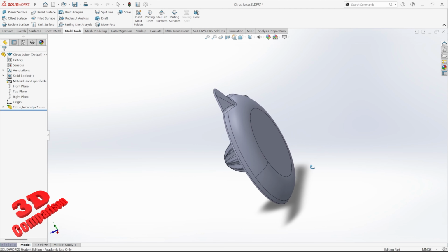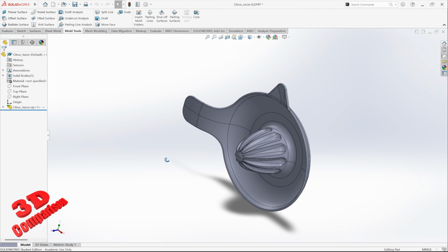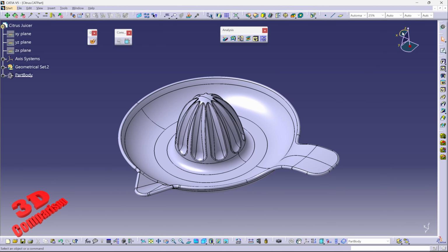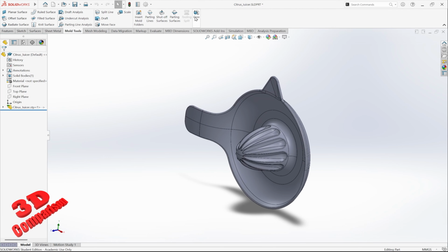And the first thing that we're going to see is that the orientation will be like this. So we have the y-axis going upwards, while within CATIA we had the z-axis. So we're going to need to go ahead and rotate the part. We could design the tooling split to open like this, but I'm just going to rotate those.